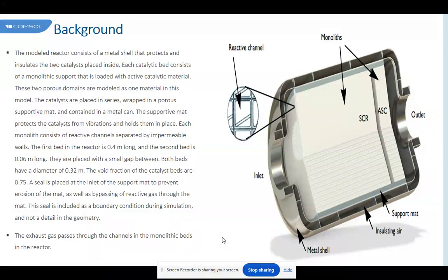In such cases, the ignited branch extends to lower inlet gas temperature, typically between 60 to 100 degrees centigrade in after-treatment applications, for the same catalyst loading. For transient operation where the time to light-off is important, it is shown that for the case of back-end ignition, corresponding to low inlet temperatures or low catalyst loading,